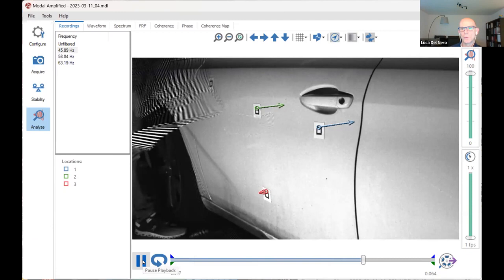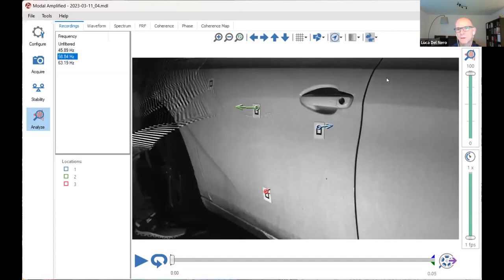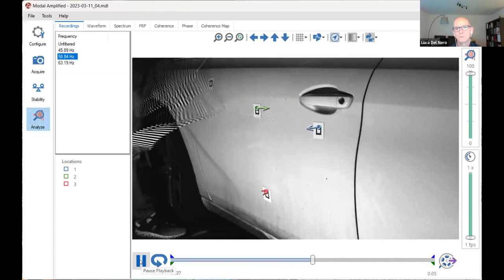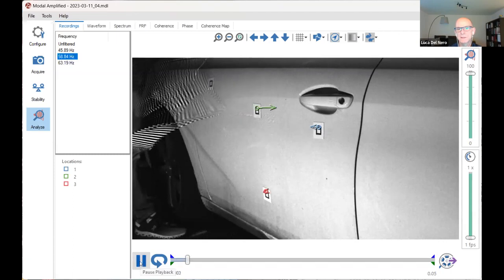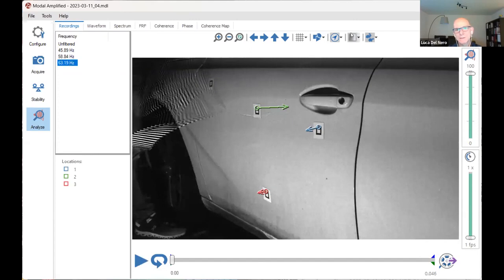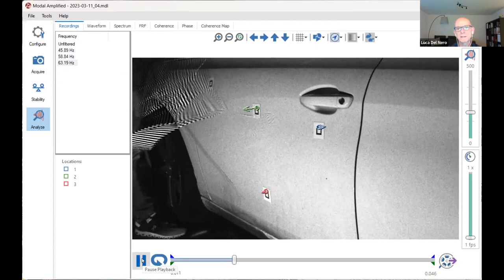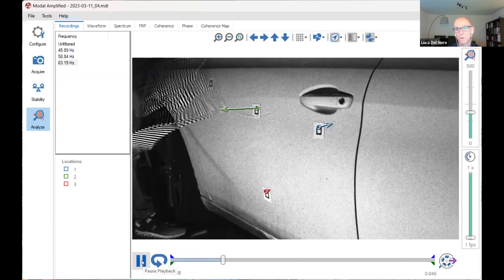and you see the door is going left to right as a single part here. And if you go a little bit higher, you can clearly see that the door has a totally different behavior. Okay, there is a torsional motion, and the red spot is almost stable, it's not moving there. While if we look at the other frequency here, that's about 63.2 Hertz, we need to increase a little bit the amplification. We see a similar motion, but this time the red area is moving more than before, while the blue one is moving less.